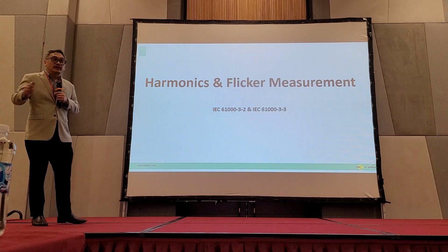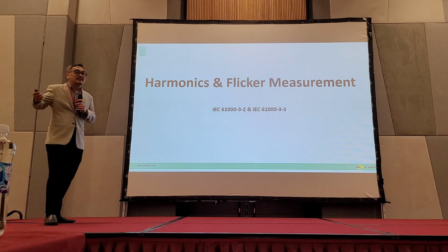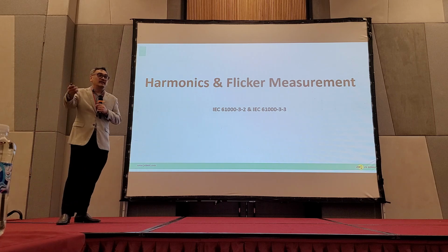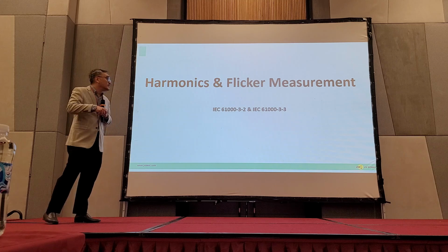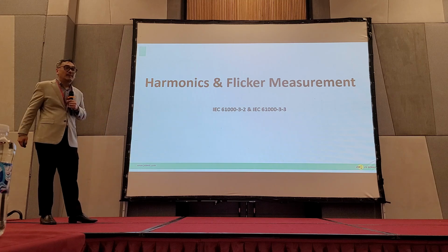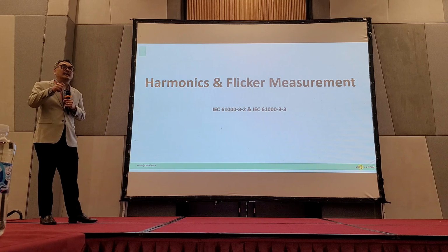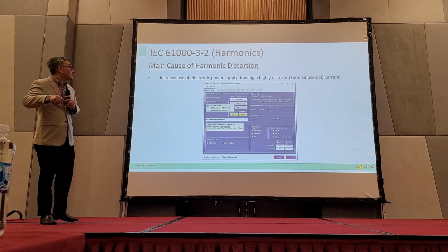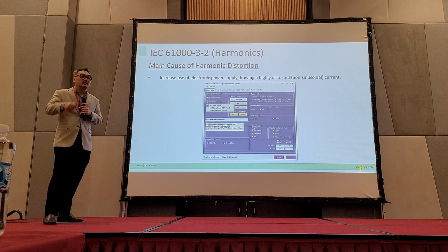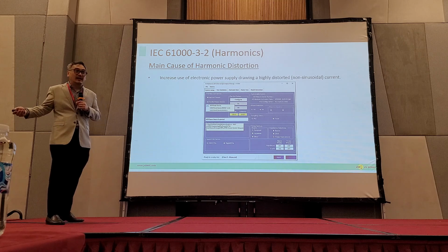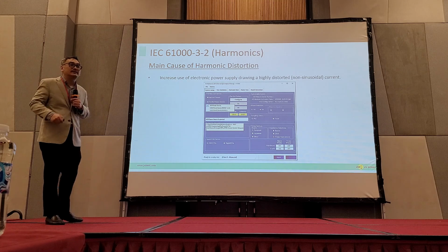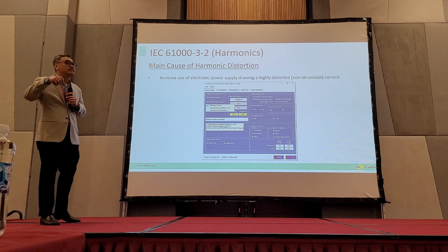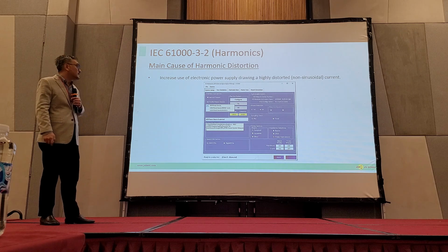So that finishes RF emission. Next, imagine a product. What else will it create? It will create noise. Harmonics means the noise in the power line. This is not RF. So we measure the harmonics with a power analyzer. We measure all the harmonics in the power line, to ensure that it is within the standard limits.